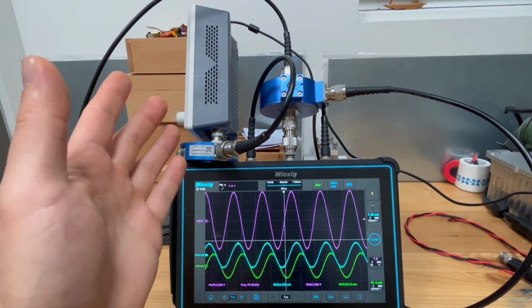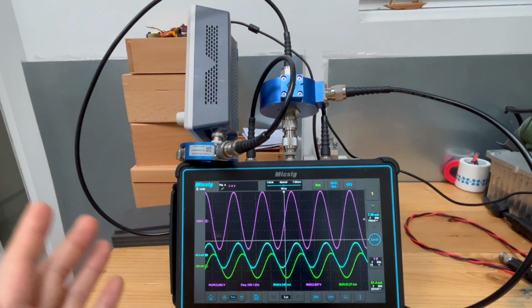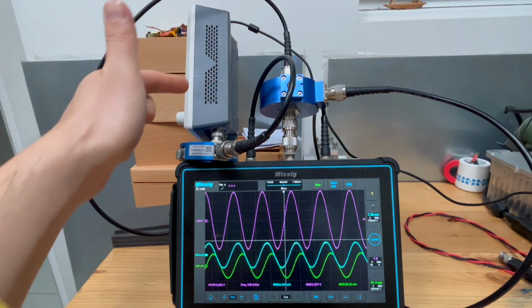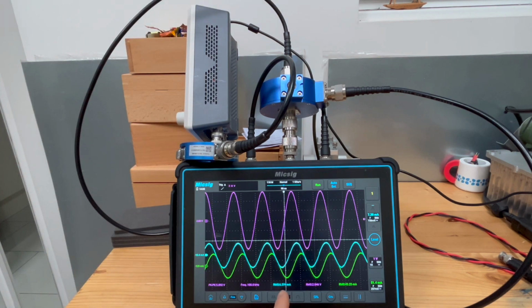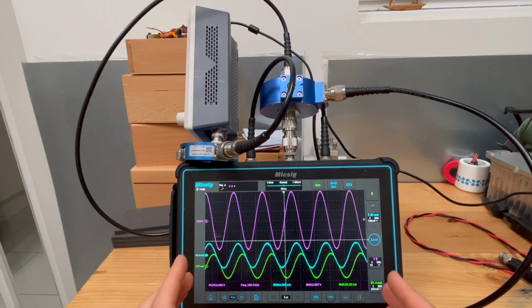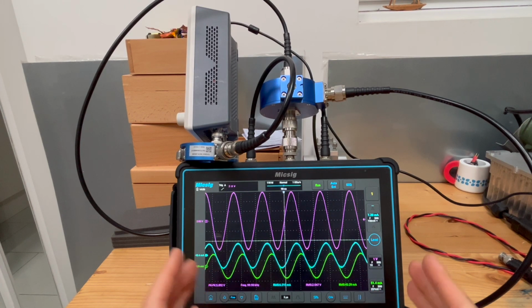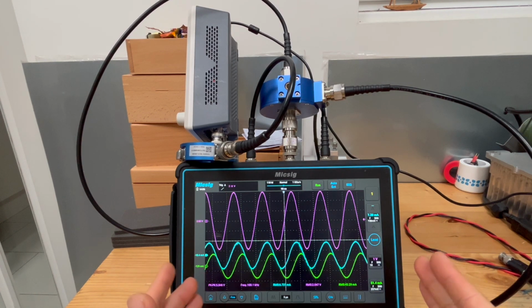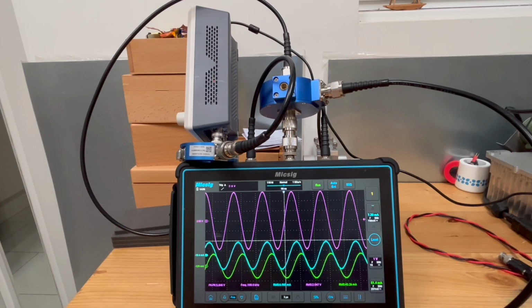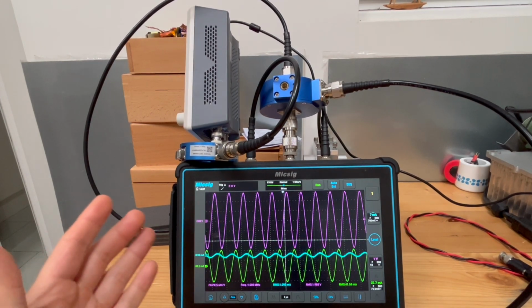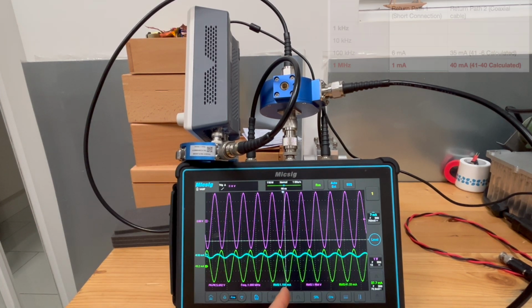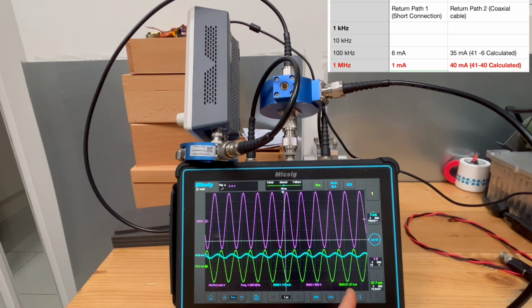Alright, so we set it up as a coaxial cable, and we just wanted to do a very quick comparison. So if you look at the frequency point, which is 100 kilohertz, okay? In this case, you can see the current going through this shorter path is now only 6 milliamps. If you remember the ratio we had with twisted pair, clearly you can see that coaxial cable for high frequency signal is a lot better. Let's do 1 megahertz just to have a look. Alright, this is 1 megahertz. Here, the shorter path only registers 1 milliamp, whereas here is about 41 milliamps.